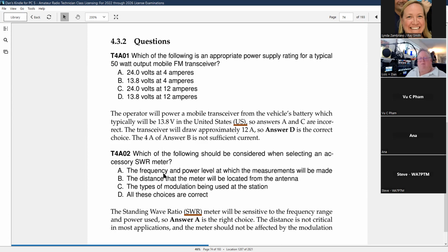That said, some radios have them built in. I have a separate meter I can use, and I have to make sure that if it's only designed to handle 100 watts and I plug in my big amplifier and put in 1,000 watts, it'll burn it up. So you've got to watch out how much power you put in, and they're designed for particular frequencies. I might buy one that works for my handheld for the 2 meter, 70 centimeter, and need a different one for the high frequencies, which are much longer waves. So you have to buy one for the appropriate frequency and power level.